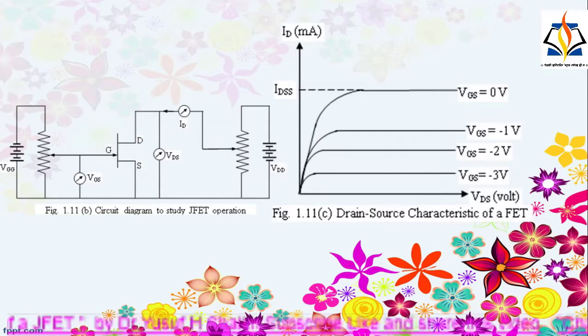As the applied voltage is further increased above a certain voltage, the current is known as the saturation current and the potential is known as the pinch off voltage, denoted by Vp. Even beyond the pinch off voltage, the channel is not completely closed. Consequently, current is not reduced to 0.